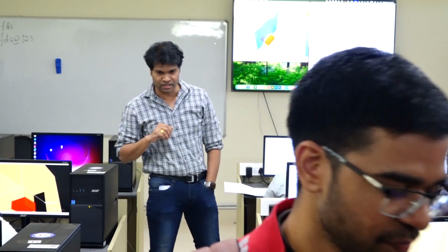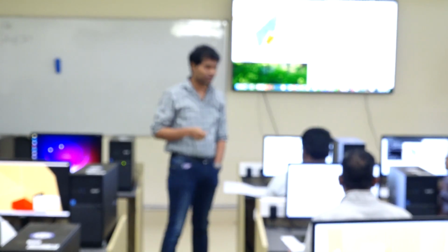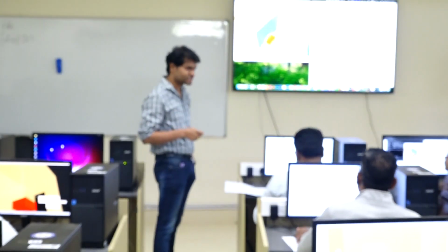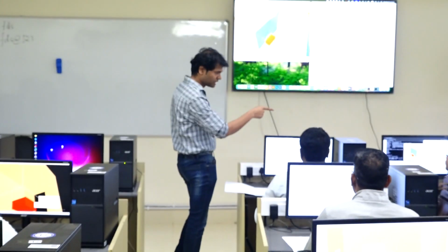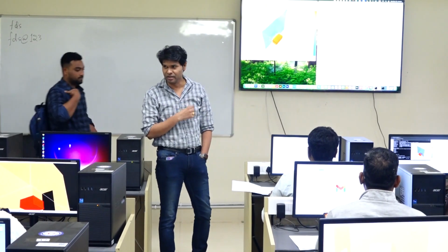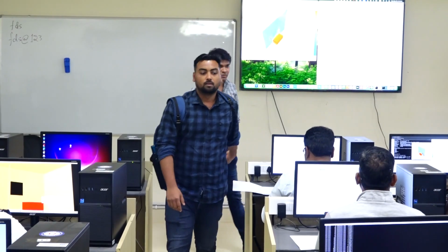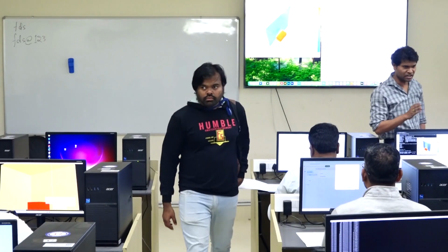FDS, when you start running the simulation, it will immediately create the assembly file. Okay? But that doesn't mean your simulation is complete. The simulation is complete when you get the message that FDS has completed successfully. Okay? And you see the real time, 60 seconds, on your command prompt. Alright? Cool. Alright, so now you have the simulation complete.